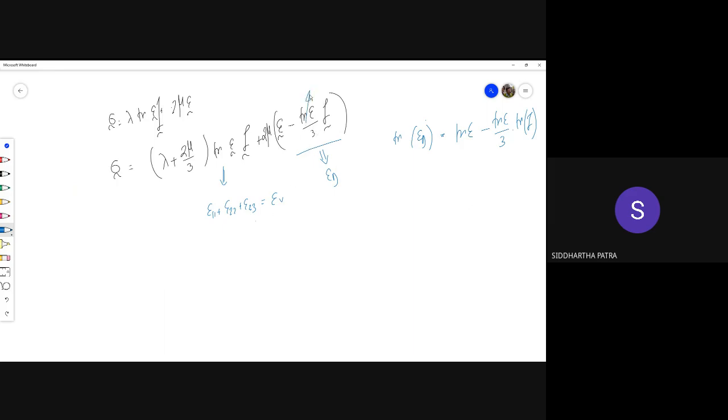So essentially, once you multiply trace of epsilon divided by 3, or epsilon v divided by 3, to each component of the identity tensor, and then you take the trace of it, you essentially get the trace of the strain tensor. So this is actually 3. So this happens to be 0. So now I have transformed the strain tensor into a deviatoric strain tensor, which basically represents no volumetric strain, but other types of strains, mostly shear strains.